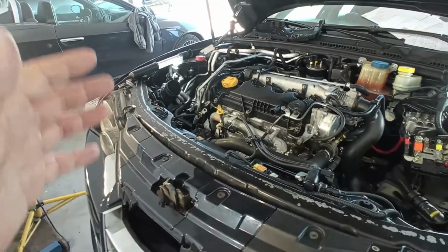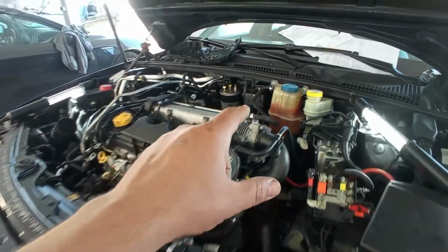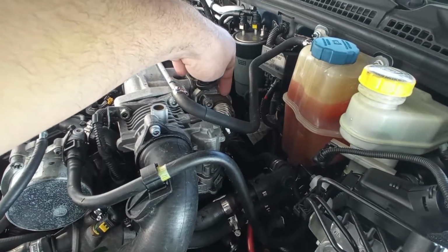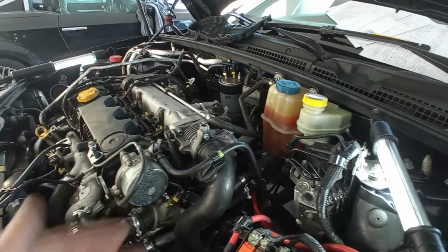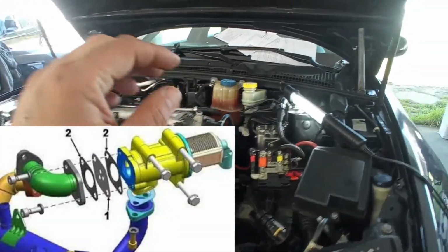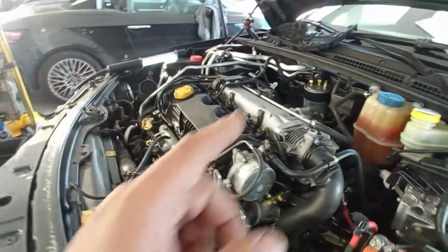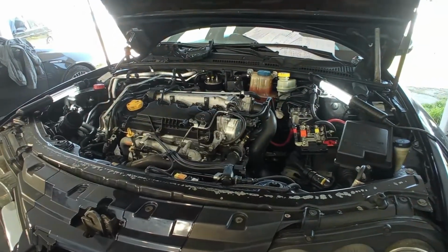And so for that, if the air is wrongly measured, if I have, for example, a problem on the EGR, because I have here a very strange gasket over here, if I have a functioning DPF, I cannot modify the EGR. Possibly just that modified gasket that I talked about on the video about EGRs. It is also down on the description, but you cannot blank it all the way, okay?